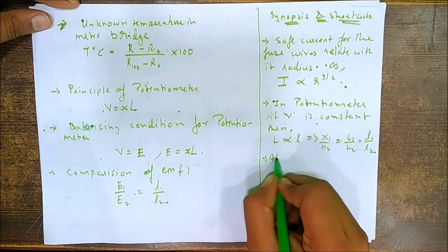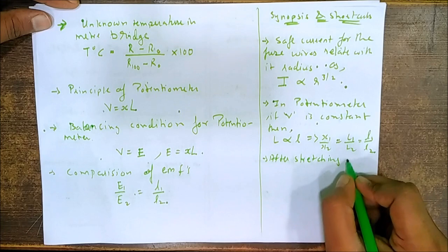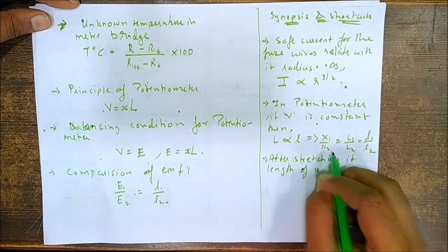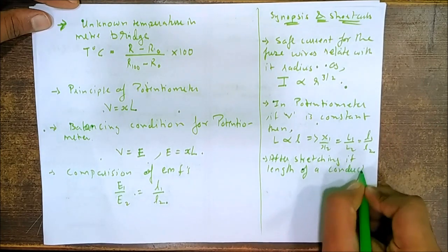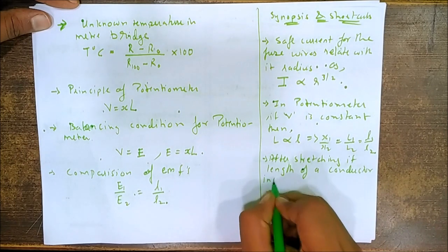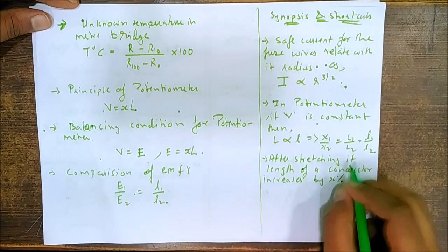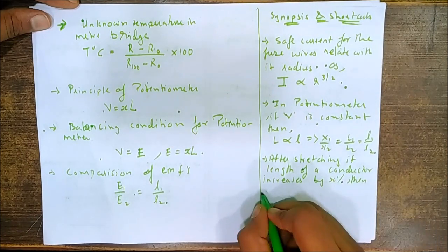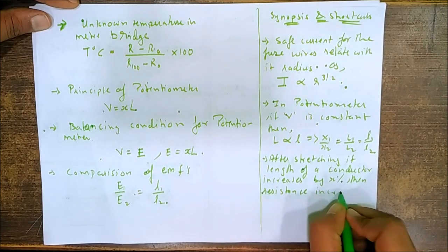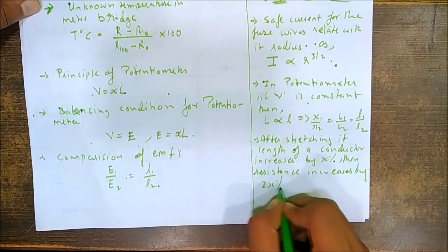Next, after stretching, if the length of a conductor, see these questions come after stretching, if the length of the conductor increases by x%, then resistance increases by 2x%.